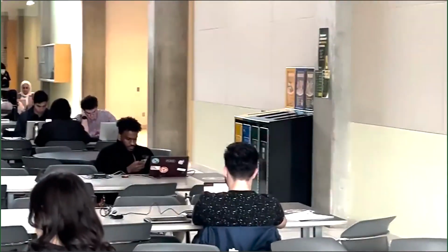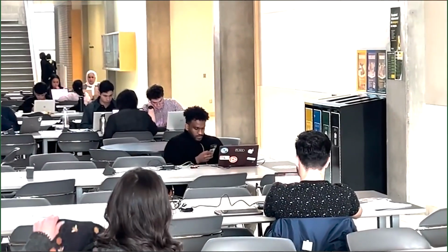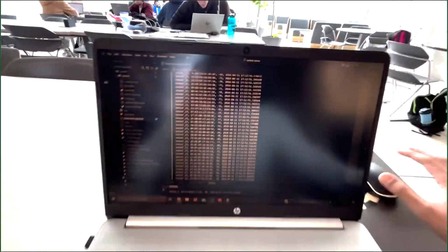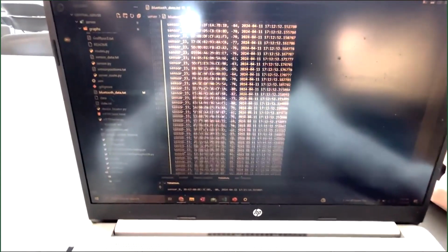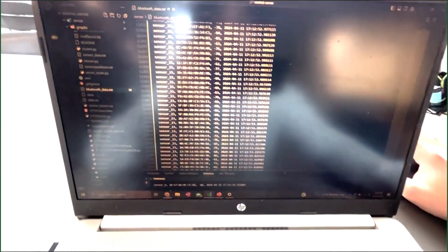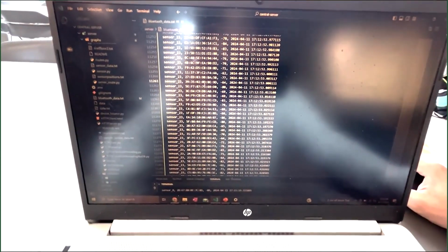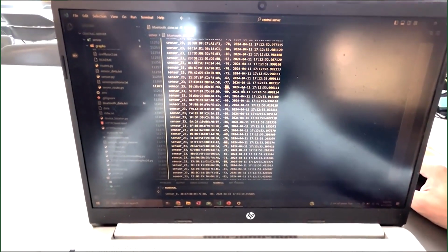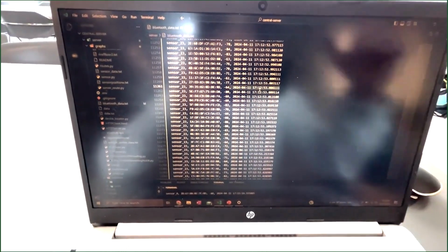And Aziz is back there. He is connected to sensor 23. So yeah, this is the data that we are going to use for the trilateration. Every message that's being received has the sensor ID, the device ID that it's detecting, the RSSI, and the timestamp of the message.